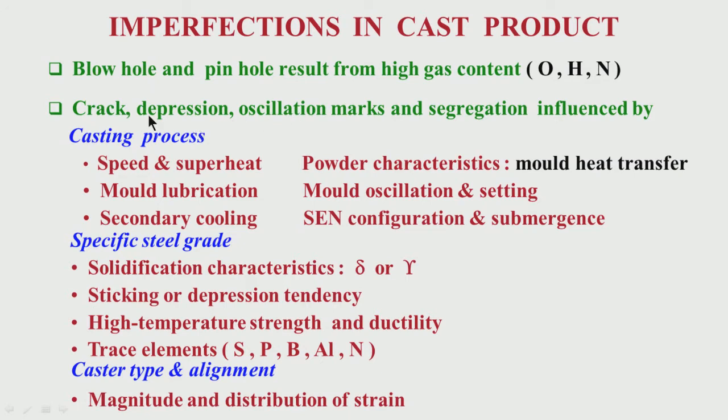Then there may be crack formation, this is very important. When the solidification is taking place, the shell might develop some cracks. As I was telling, the shell has certain properties. It is at high temperature and finally slowly coming down to low temperature. So, at high temperature, what is the strength? What is the toughness of the solid shell, whether it is delta or gamma? They have different properties at high temperature.